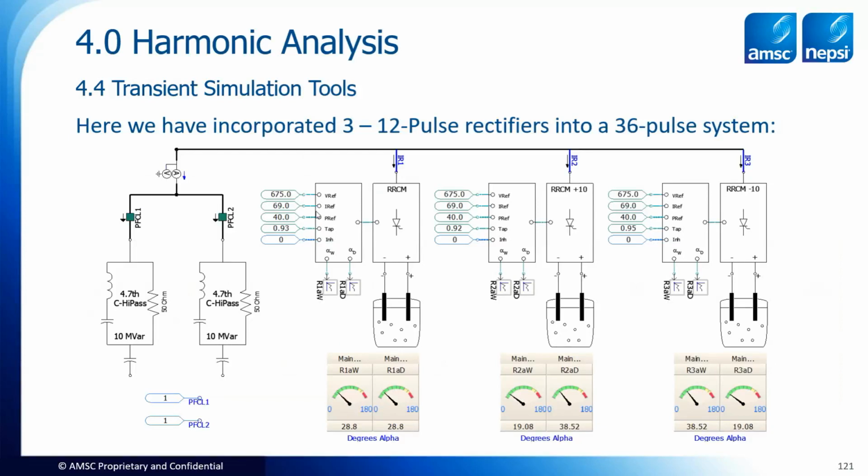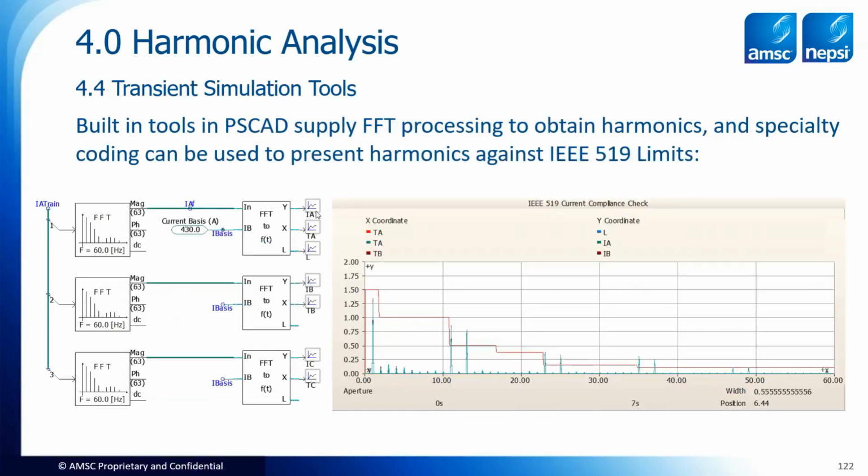Upstream of this, I have to see what the total current is, and if I want to judge it, I have to analyze it. And they have those tools, for instance, in PSCAD. That's what I've been showing you. It has an FFT, a fast Fourier transform, to take the waveform, just like you would do with a power quality meter. Literally, just like you would do in the field.